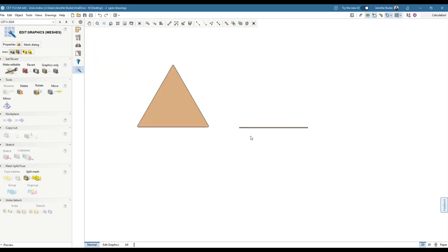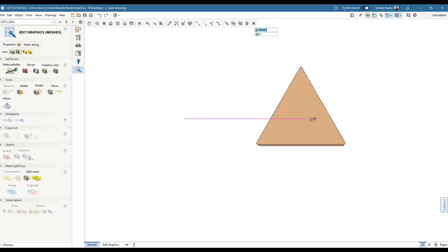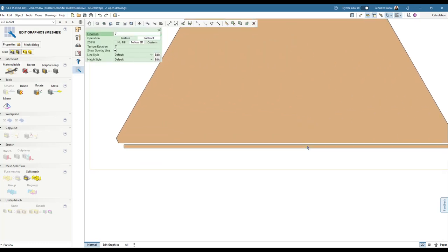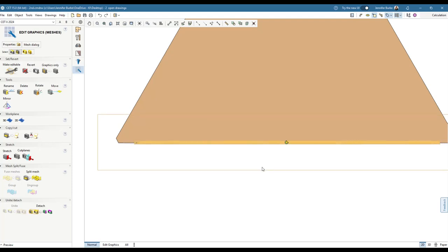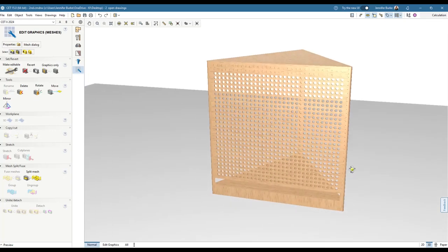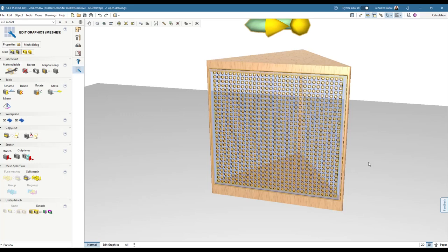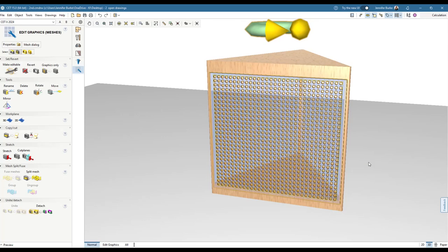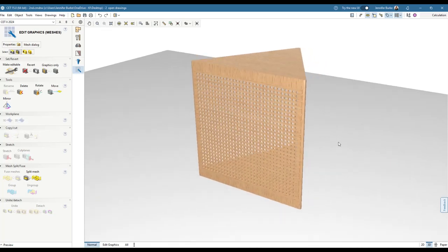Like anything, you can click in the 2D view and manually move this over, get this centered like that, and get this moved in just a little bit. We want to make sure we can still see the edge of the frame protruding out, like that, for example. Then check your 2D and use page down to get it centered. You can also hold the shift key and page up or down to get it in smaller increments. Everything looks great.